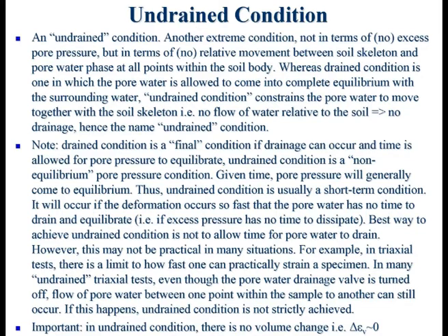Now, in practice, just saying a little bit about the way things are practiced in Singapore. Usually, if you do a FEM, of course, the best way to do FEM is to say, I will run it with the soil dissipating the excess pore pressure. That's called consolidation analysis, with the soil dissipating the pore pressure as it goes along. That is the best way to do it. But a lot of engineers, somehow, I don't know why, are afraid to run consolidation analysis.